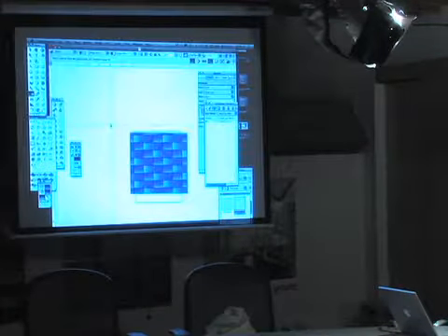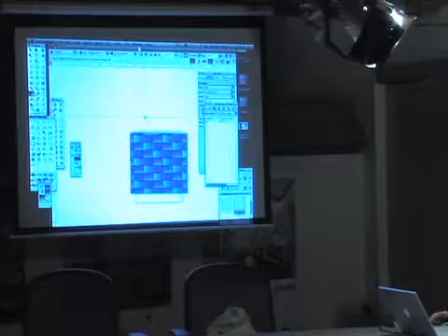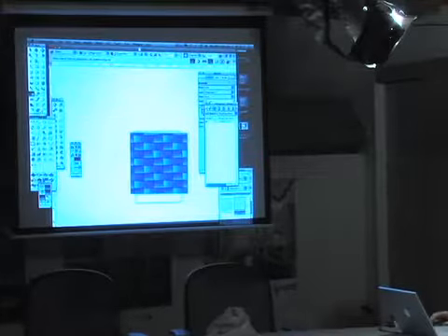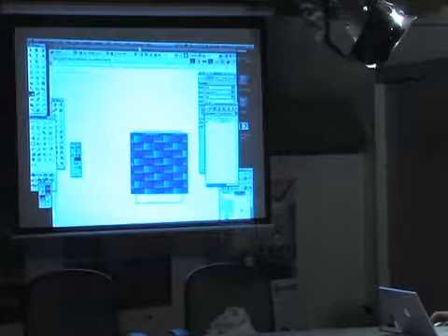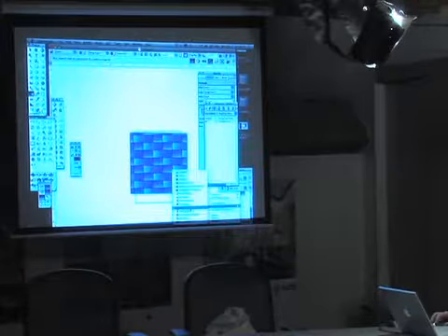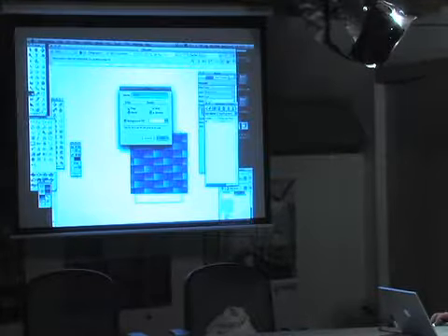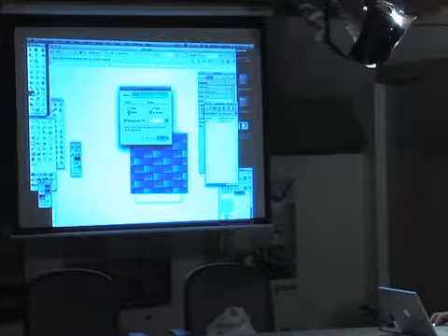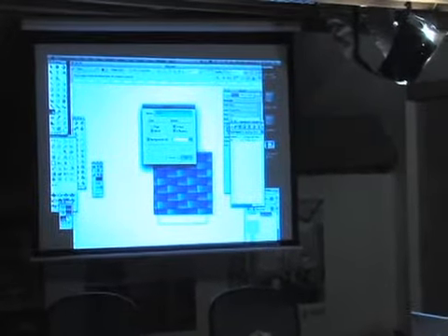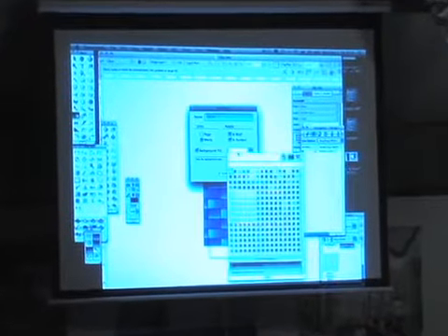You want to be able to proportion the thing. So with tiles, now you can draw any object, and it'll make a tile pattern. So now let's add a new resource called a tile here, and you can orient it to page size or world size, so it stays scaled to your drawing. Apply it to your wall or symbol, rotate it, and choose your background fill.